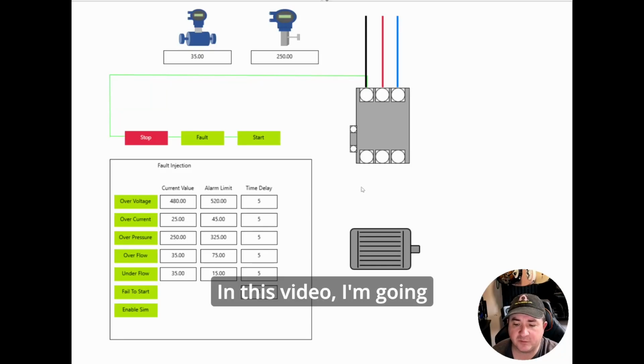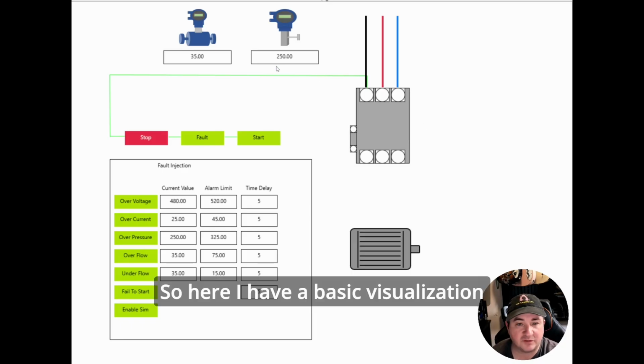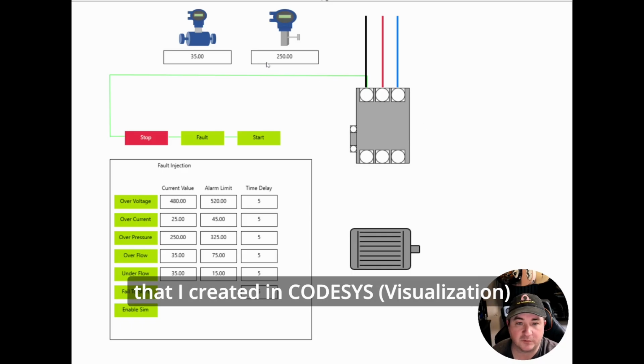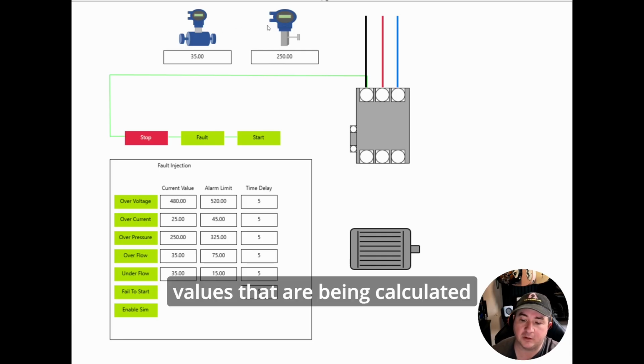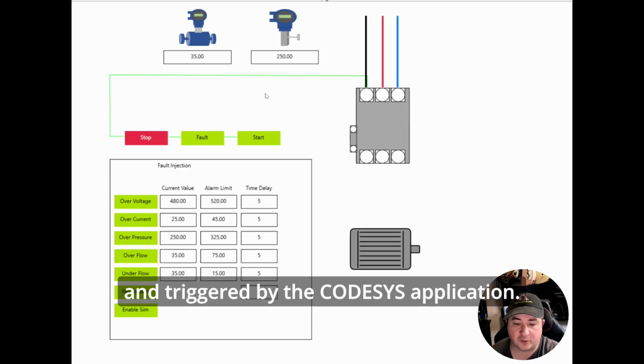Hello and welcome. In this video, I'm going to demonstrate the creation of a program for a simple motor control circuit. So here I have a basic visualization that I created in CODESYS. This has some simulated values that are being calculated and triggered by the CODESYS application.